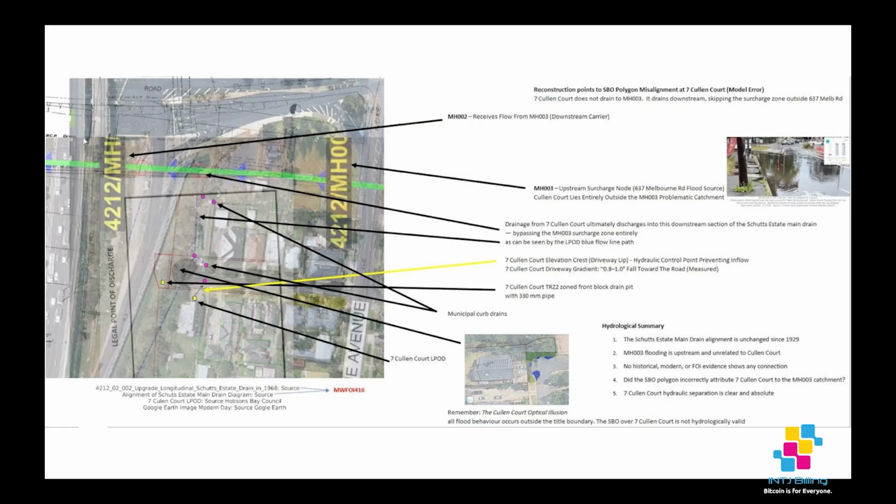And of course, we've got the Westgate Freeway embankment over here, which has been upgraded, where there's a new retaining wall, and there's 4 new drains across here to the left. All right, and to the far left, as you can see here, this handwritten line from the 1968 image refers to the creek, Stony Creek. Of course, Stony Creek has had many upgrades since the Westgate Freeway went in. One need only go and have a look at Stony Creek to see just how significant the drainage infrastructure is.